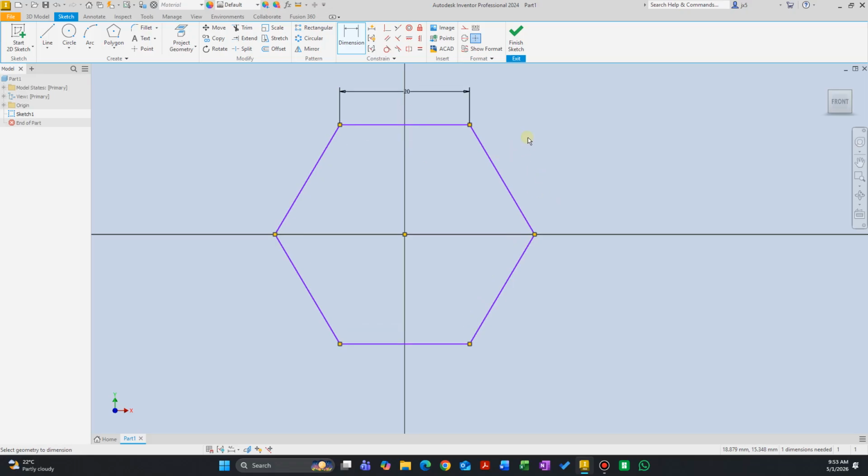And I see that people who are starting to learn a CAD software run into this a lot. They don't know what the second dimension is. As you get familiarity with the software, you can do this pretty quickly. But say you couldn't figure out what to dimension next. So let's say you dimension this, for example, and you get an error saying that this is over constrained. So it is asking for some kind of a different dimension.